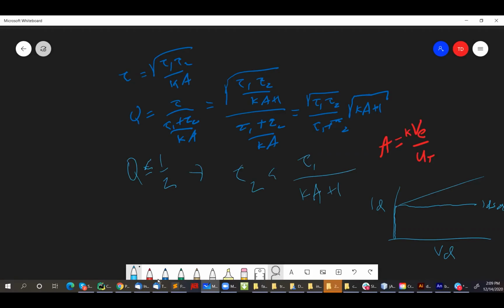Plus this drain current component, the early voltage component, where this intercepts back here at minus VE, where this GM here is equal to ID sat over the early voltage. So this is like a constant current part here, and this is the parallel conductance part. Okay, and that was mathematically how the subthreshold equation was defined in our notebook. It's this ID sat plus exactly this parallel conductance. At least that was how it was supposed to be.